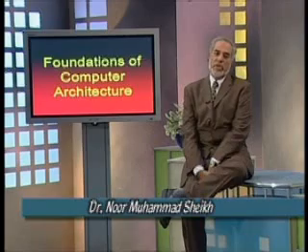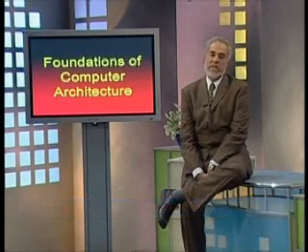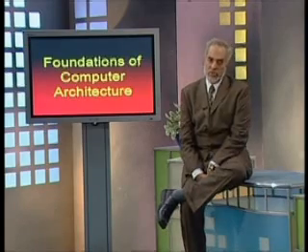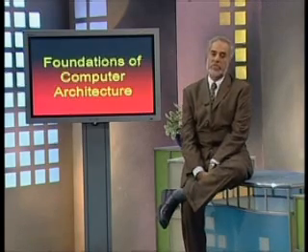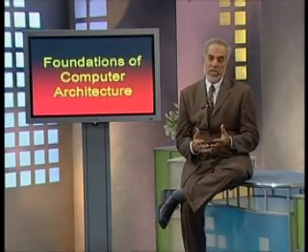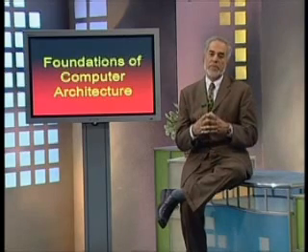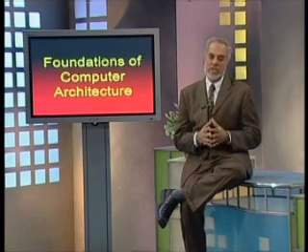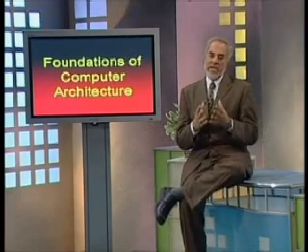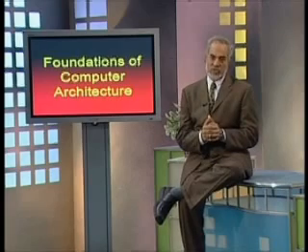Now, why do we prefer to use RISC? In a given clock time, which is gradually decreasing, when we increase the clock frequency, the clock time would decrease, and the instructions should be such that we could complete it within one clock cycle. Now, that gives a simplicity in the case of RISC.